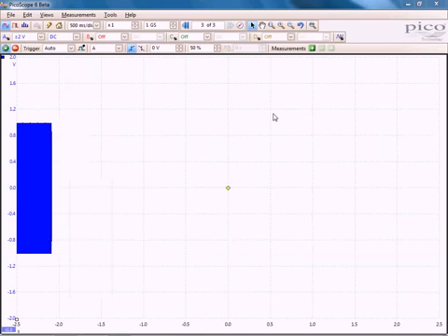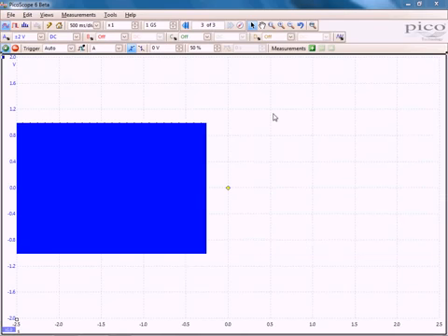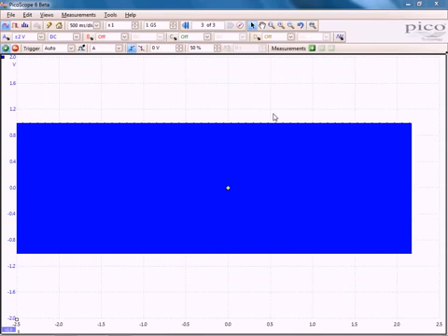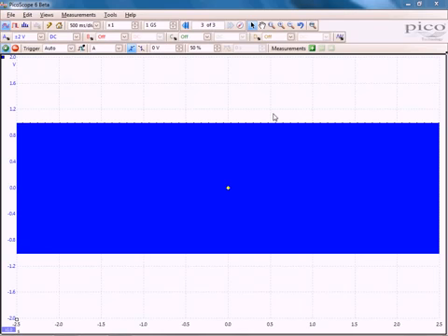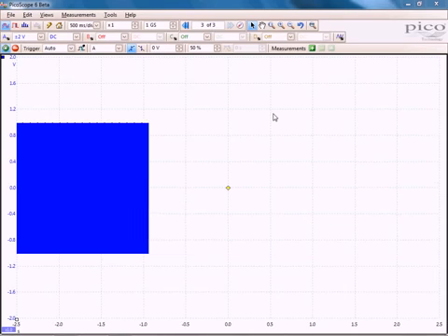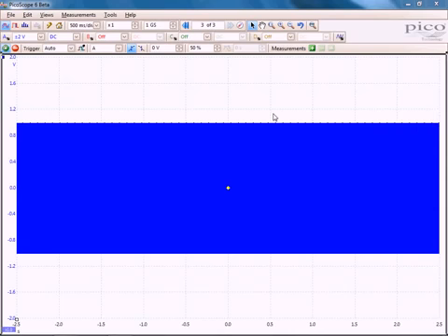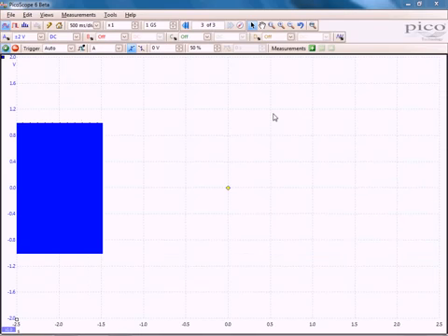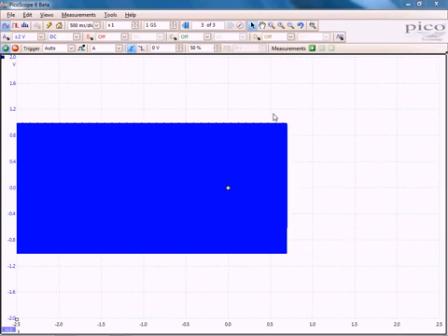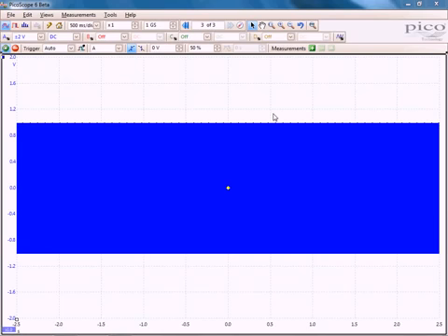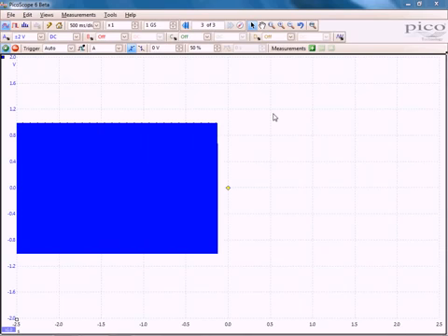The next great feature I would like to talk about is the faster USB streaming sampling. At longer time bases, more than 1 second across the screen, data is drawn on the screen at the same time as it is collected. In this mode, data is streamed continuously across the USB link. We have made some significant improvements to this USB streaming, for which most devices currently on sale has increased the streaming sampling rate from 1 million samples a second to 10 million samples a second.